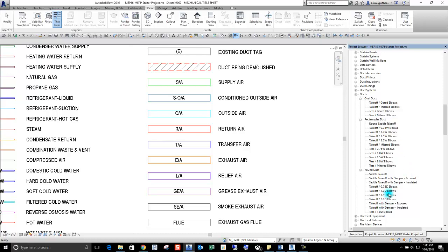As you know, Revit has some takeoffs with dampers in them. So we've called those out, and we've also identified which duct systems have insulation and which ones don't. So in round duct here, if you had a takeoff to a grill and it was exposed, you could choose this option. If you have insulation on your ductwork, then you would choose this option. Of course, with each duct type, we have different elbow options and T options as well.